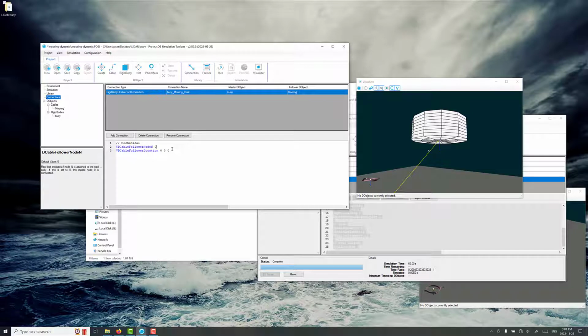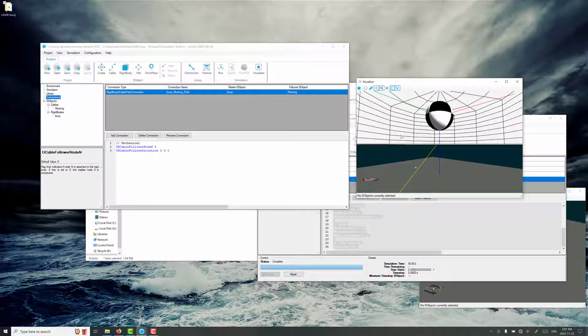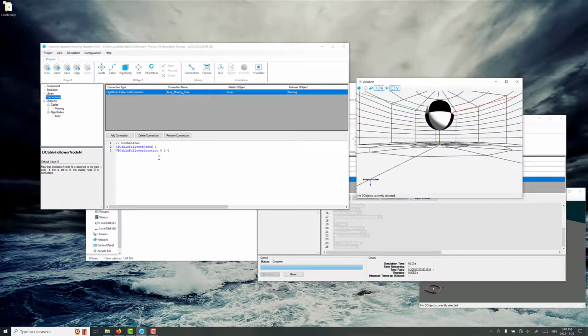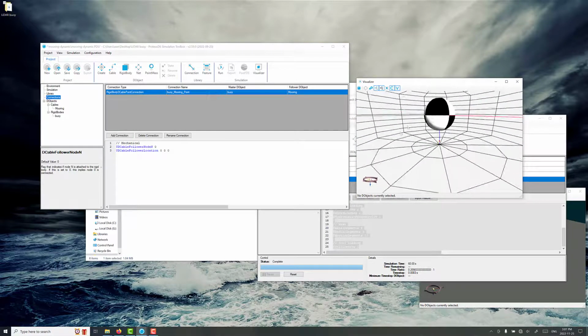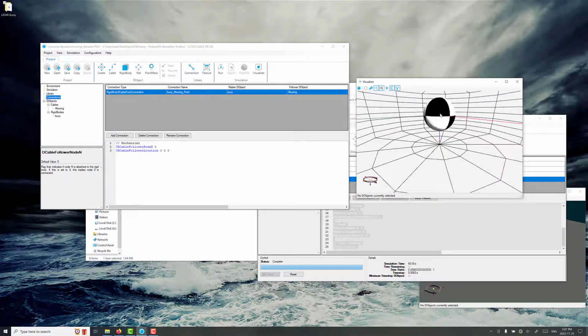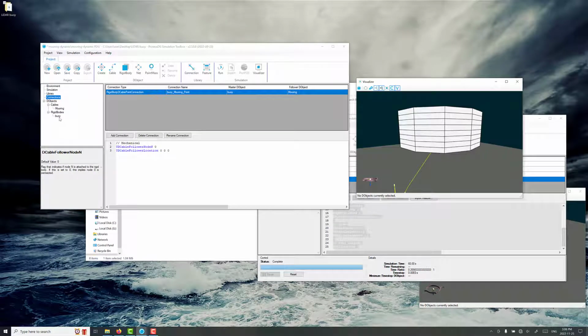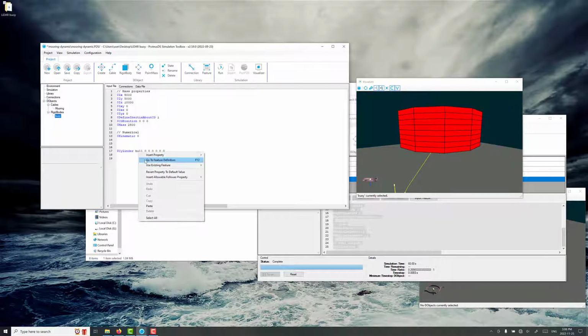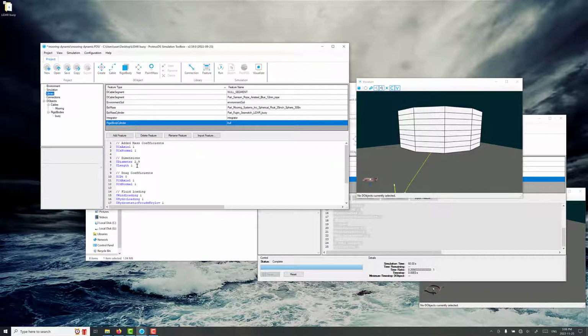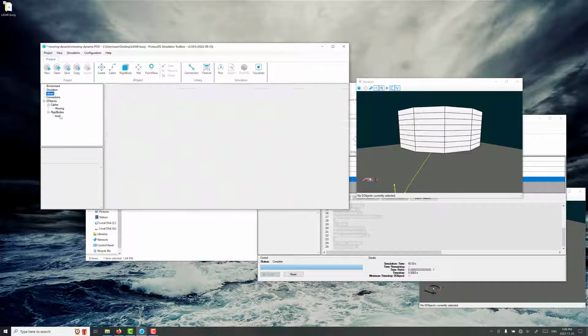So is it constraining node N? No, it is not. And now we need to express this connection location in terms of the rigid body frame. I've just made a very quick model of the rigid body buoy. I've left the rigid body frame in just at the very center of everything, and I know the cylinder hull is 1 meter tall. Let's double check that. There's our length, yes. So it's half a meter from the middle to the bottom. Maybe we'll give it a little bit of extra space off the bottom.